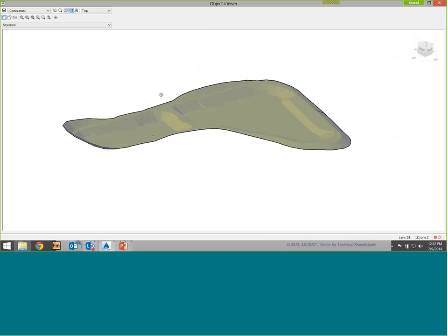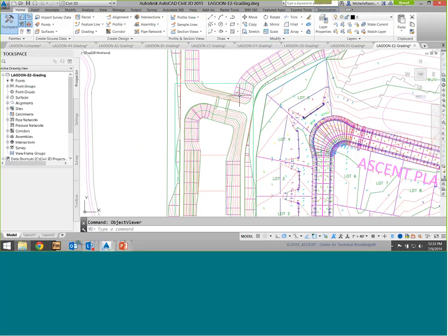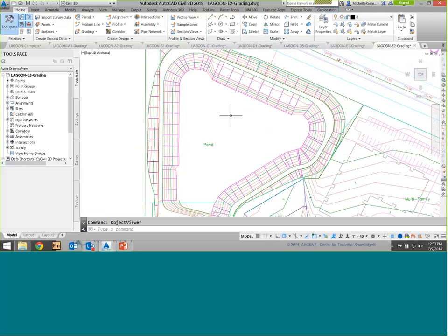But unfortunately, gosh darn, what ends up happening? I had a design change. If this were done with grading objects, changing that would be very, very difficult. Especially if I had a complex grading object where I graded one object off of another, I couldn't just go in and modify the feature line that one grading object created. However, I can make quick modifications to the corridor model.